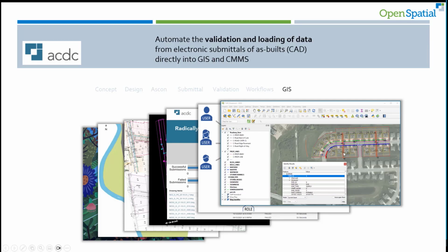Yeah, we're showing the data in QGIS, but you'll see you've got diameters, materials, and part of the validation process is creating connected attributed networks for utilities specifically as rules that you can add so that you, for example, get all of the pipes segmented where there are short stubs between, say, a valve and a fitting. We even include that. Split that out so it's all ready for modeling. So there's a lot more power than just taking lines and throwing them over the wall.